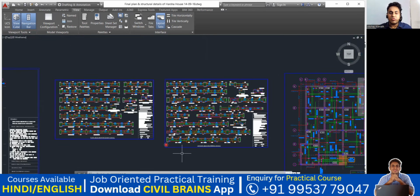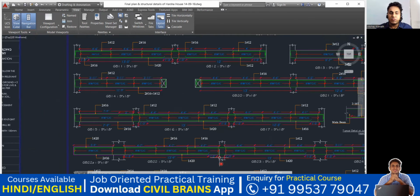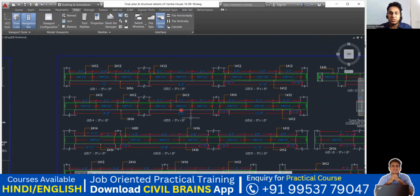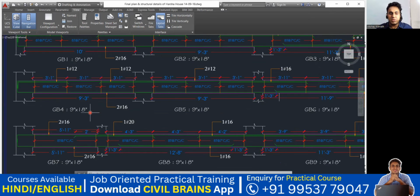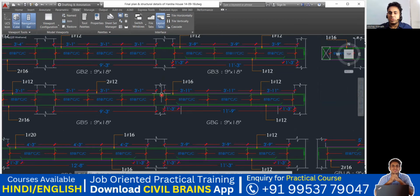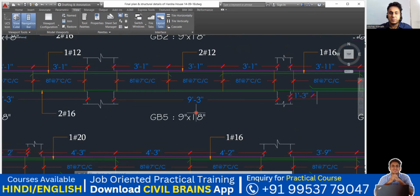So for that I need to refer to this one, that is ground beam shuttering details. It is not shuttering again, it has to be reinforcement. There's a mistake here. I'll go for GB5. So my GB5 will be somewhere here. Yeah, this is my GB5. So you can see this is my GB4 beam. This column to this column, whatever beam I'm getting, it is GB5. And from this column to this column, whatever beam I'm getting, it is my GB6. Great. So let me look into the GB5 reinforcement details.